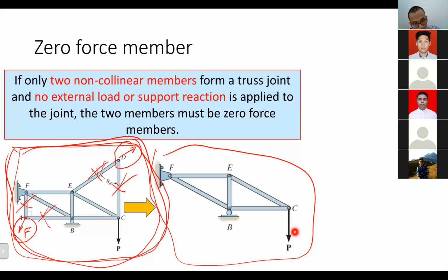Like the force is not on joint A, but on the body of the member. In that case, it's not a truss anymore. Remember, a truss system consists of two force members only. Two force members, the force can only be given to both ends. It's either like this or like this.